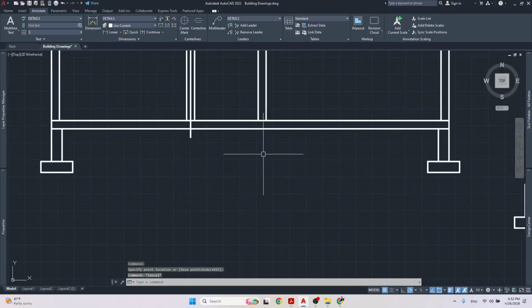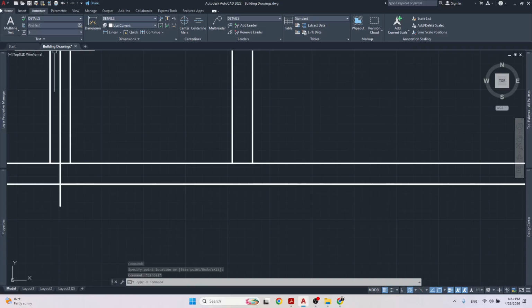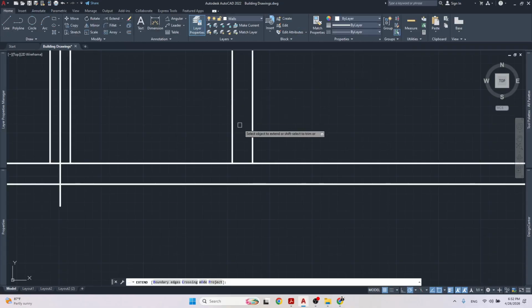That's where my center would be. The other way to do it would be to extend these two lines and then draw an X from the corners, diagonal lines. Where these two diagonal lines cross, that is the center of these two lines here.